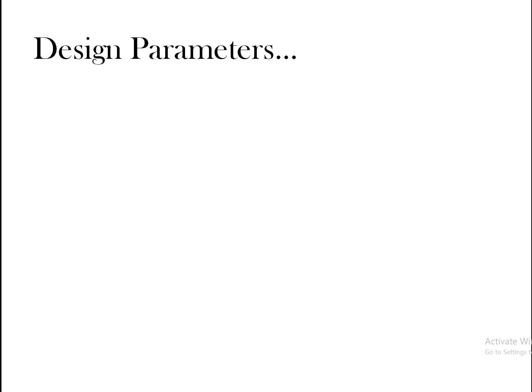So what are we designing? As we have already seen in our previous lectures, starting from the design of machine elements 1 itself, by the term design we actually mean finding the basic parameters or dimensions of a particular component, be it a rivet, be it welding, whatever it is. We find all the dimensions of the component for a particular application. That dimension is selected based upon the external factors acting on the material, for example, the power which needs to be transmitted.